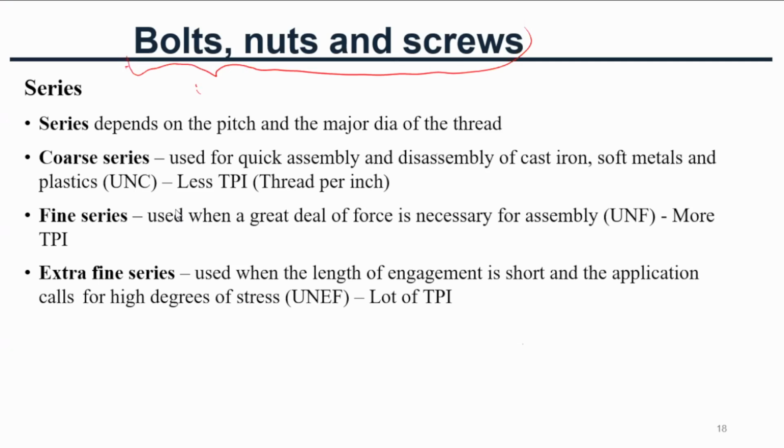We take the dimensions of the thread and its pitch, that is the minor diameter, major diameter, and pitch diameter, and according to these we identify the standards. As in the table, according to the standard tables we can get standard values.